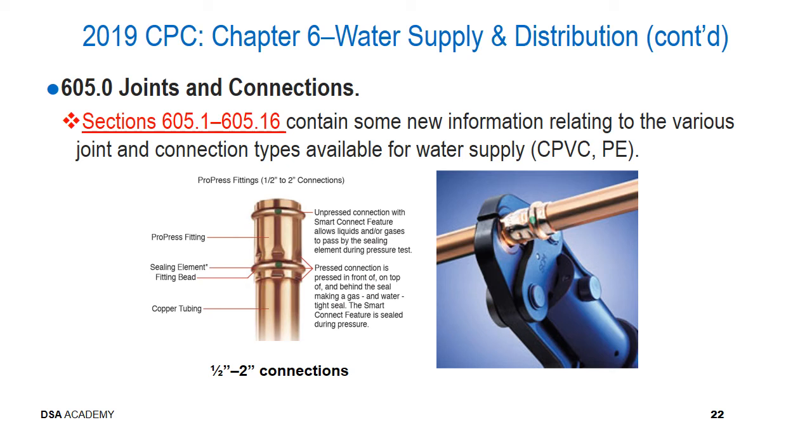And because it's an installation process, the details will probably be identified in the approved specifications. So again, to reiterate, it's extremely important that you use the approved plans as the basis for your inspection for what is compliant for each project for joint connections.